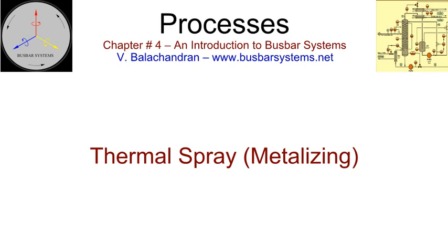It is ideally suitable for large objects, such as masts and towers, that cannot be hot-dip galvanized due to their sizes. Spraying can be undertaken on objects that would otherwise distort due to heat when hot-dip galvanized. The deposition can be much higher and can be undertaken by spraying multiple layers. A thickness of 250 micron coat is possible.